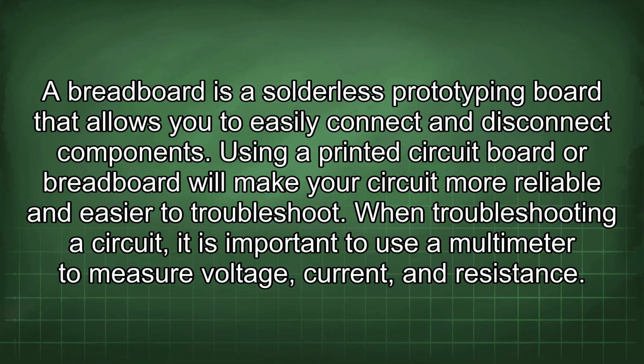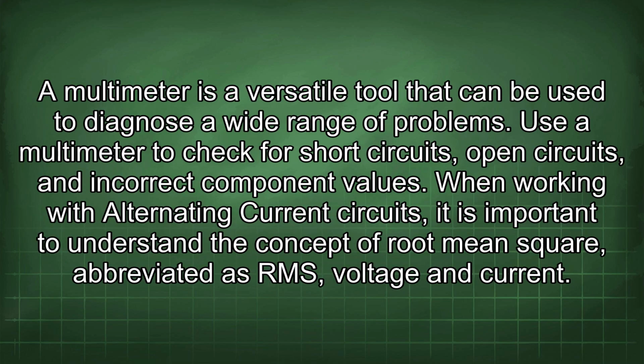When troubleshooting a circuit, it is important to use a multimeter to measure voltage, current, and resistance. A multimeter is a versatile tool that can be used to diagnose a wide range of problems. Use a multimeter to check for short circuits, open circuits, and incorrect component values.